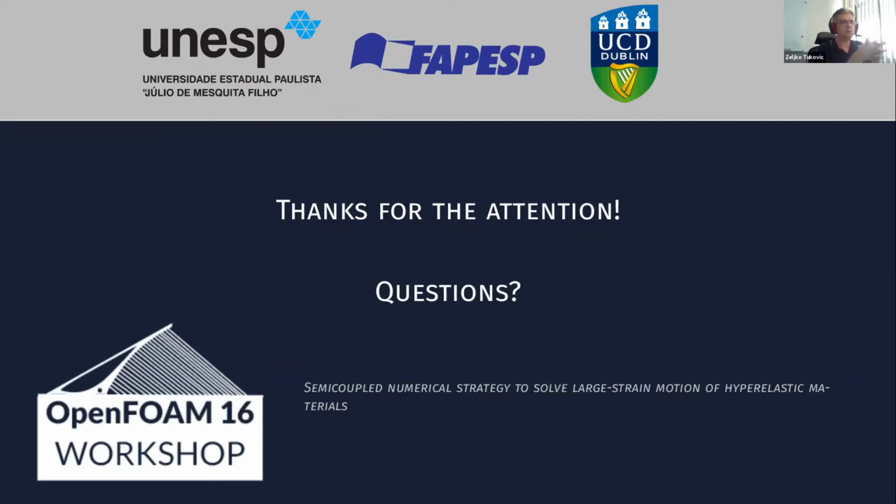Yep. I was going to say that what we saw in the displacement based, well, as far as I talked with Professor Cardiff, was more related to it may appear near the boundaries, and the reach-out correction may help with the oscillations, at least in the segregated solver. But for that case specifically, the only way that I found to at least dampen the oscillations was to refine the mesh.